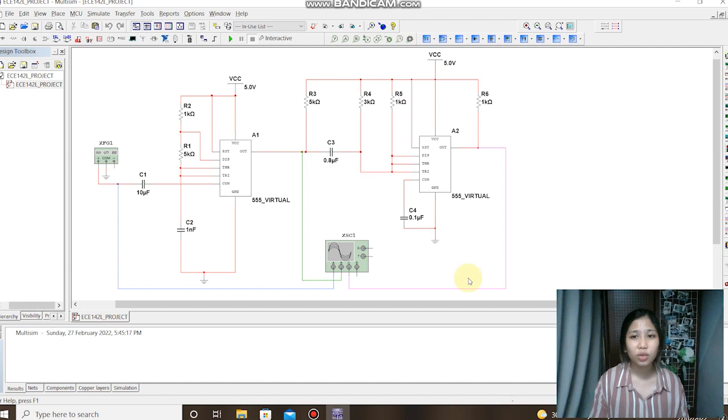When capacitor C1 is charged up to about 2/3 of VCC, the flip-flop is triggered once again, this time making the pin 3 output low, and turning on pin 7's discharge transistor, which discharges C1 to ground. This circuit, in effect, produces a pulse at pin 3 whose width T is just the product of R1 and C1. For example, T equals R1 times C1.